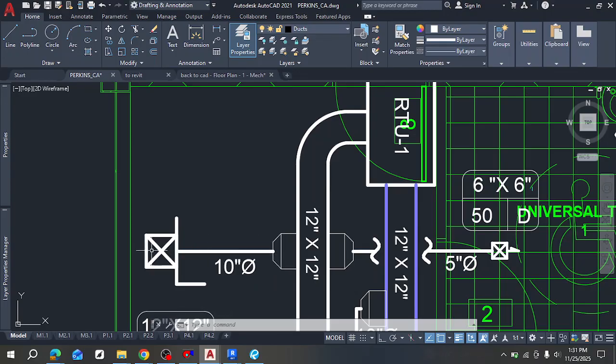So this is the flexible duct. I use just a line to simplify it. Revit has its own flexible ducts, but I don't really like the way it looks. Yeah, I don't know. I've not checked if the latest Revit has a better looking one, but I'm more comfortable using a line because I don't like too many clusters. The one on Revit has several lines. So it makes the work a bit cluttered and it's not very easy to manipulate, because solid duct is just straight, but flexible it moves. It's like an arc. So just to save myself stress, I prefer to just use a simpler line to express it.